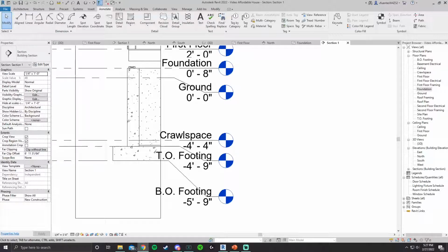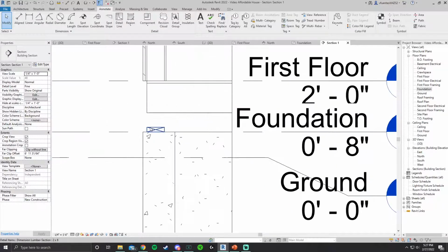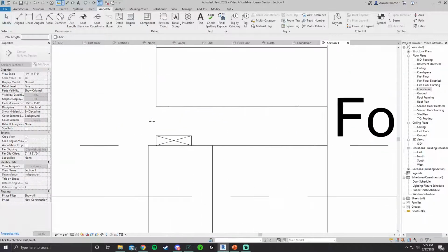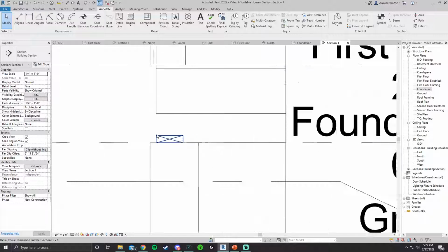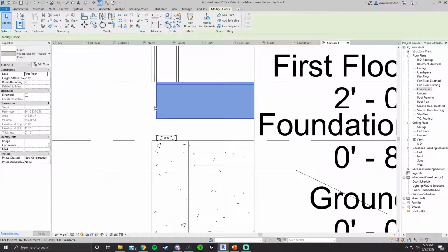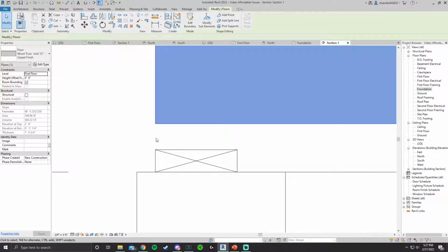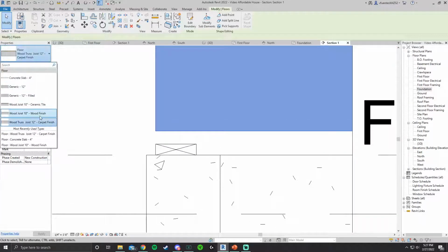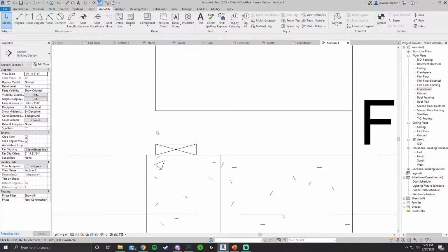Yeah, that's good. So next, I'm going to be moving my whole floor onto this sill plate. So again, if I use my measuring tool up here on the top left, I select the bottom of my floor to here. I have 4.5 inches. I want to move that down directly on top of this. Now, for my floor here, if you have a finish on it, it might be bigger than 10 inches. If you have maybe your carpet finish, you can see now you have 12 inches. It depends on what size floor you have. So I have it on my 10. That's great. Like I just measured, I have 4.5.